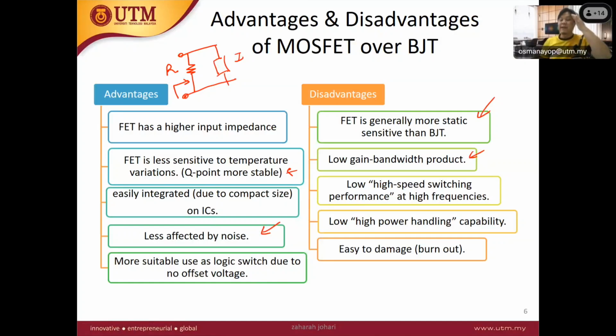Okay, if you still remember how we plotted the frequency response of the BJT in our last subtopic, we can see that we have a lower cutoff as well as a high cutoff of the BJT, due to the capacitors of the circuit. So it has quite a high bandwidth for BJT, but for MOSFET it is a little bit low, both gain and bandwidth.